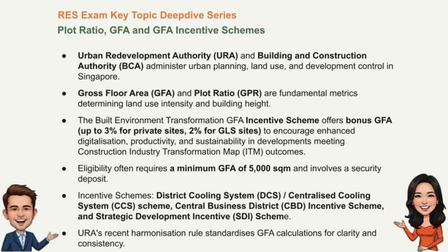1.2. What is gross floor area, GFA? Okay, so if plot ratio tells us the intensity or the potential, how much we can build relative to the land, then GFA is the actual how much itself, right? The total area. Precisely. Gross floor area, GFA, is essentially the total constructed floor area within a building. Measured how? It's measured typically from the outer walls. And critically, it encompasses all the covered floor spaces and usable areas.